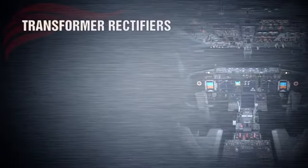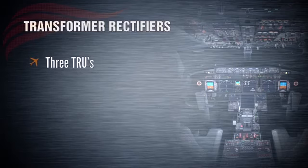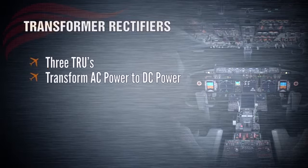We mentioned the TRUs before, so let's explain them now. The 737NG has 3 of these components, which essentially transform and rectify the 115-volt AC power to unregulated 28-volt DC power for the DC buses.